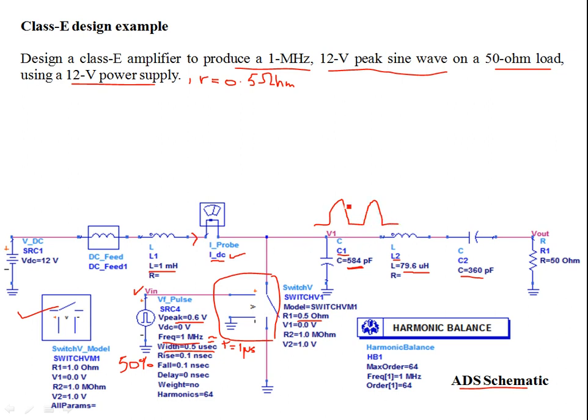This will contain a DC, and this also contains the harmonic content. The DC is the average. Alternatively, when the switch closes, you have 0, the node is shorted out. So this DC is filtered out by the coupling capacitor C2, so you won't have any DC at the Vout. You will have a nice sine wave, right?